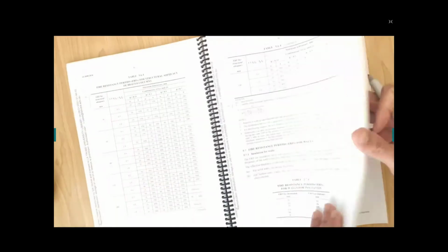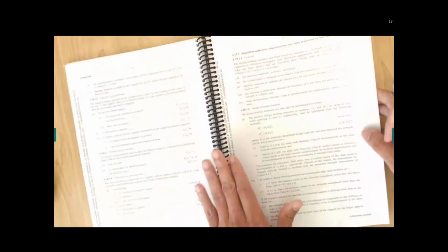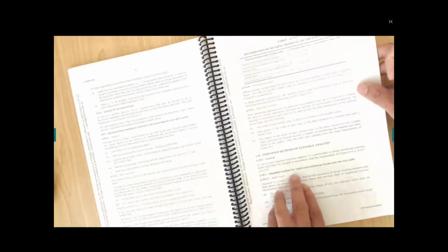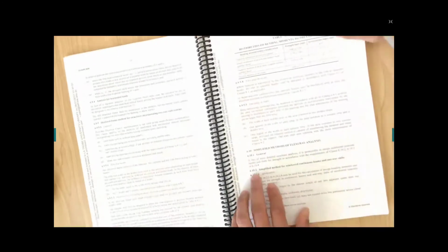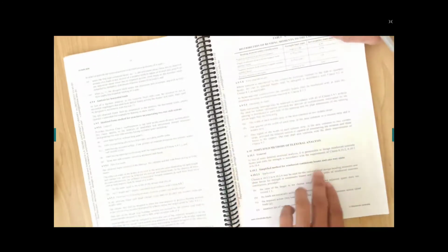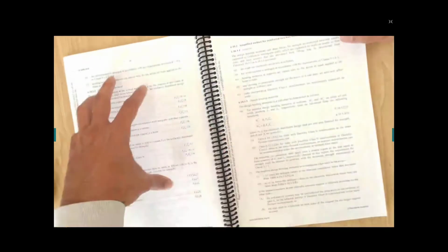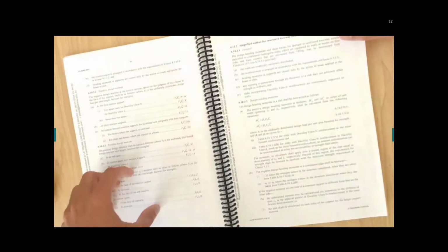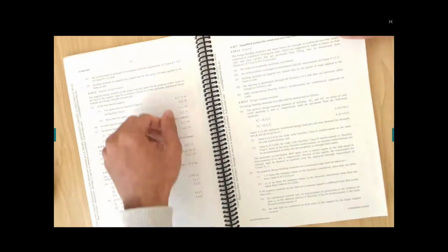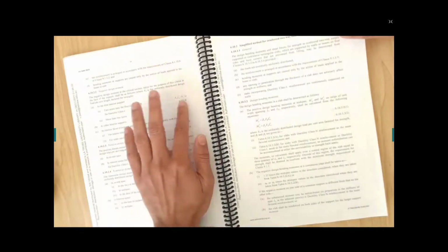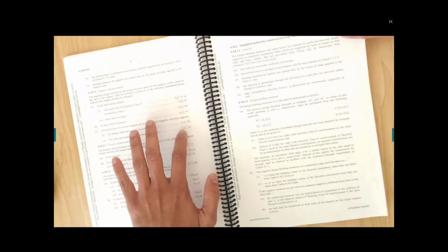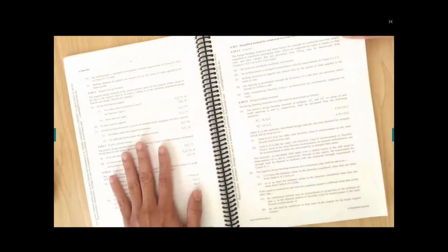Now, first of all, we need to calculate a design action. Design action means what is the moment coming onto the slab. If you remember for one-way slab, clause 6.10.2, I spent about half an hour or 15 minutes showing you how you can calculate the positive and negative moments and shear force in one-way slabs. If you remember that Fd, Ln and so on, Ln is the clear span, and Fd is 1.2 dead load plus 1.5 live load. That we did for one-way slab.